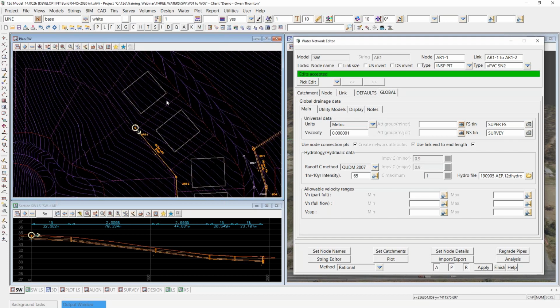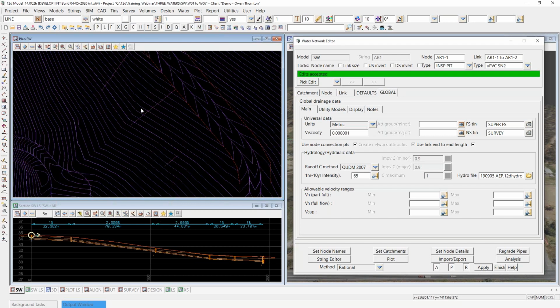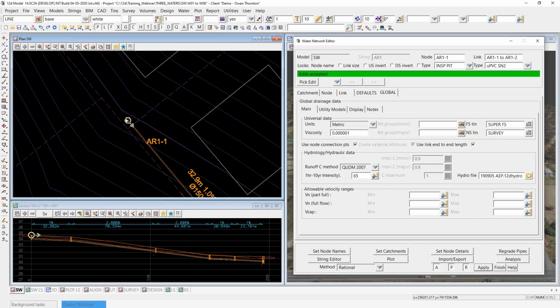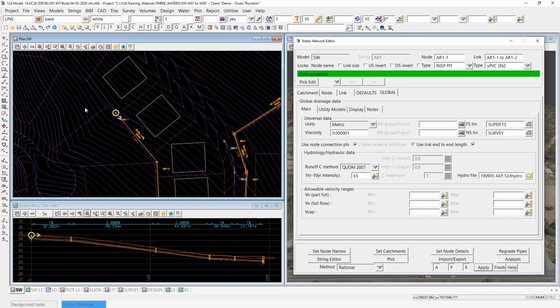In other words, you can imagine that there are gutters and downpipes on all of these roofs that will be connected through underneath the backyard there directly into these pipes, these orange pipes running along the back of the lots. Now there's no open grate or open inlet in the backyard there, so it's not going to pick up the flow outside or off the roof, just if flowing in the garden. It's only going to be picking up the down pipes from the roof. So it's only for roof flow only.